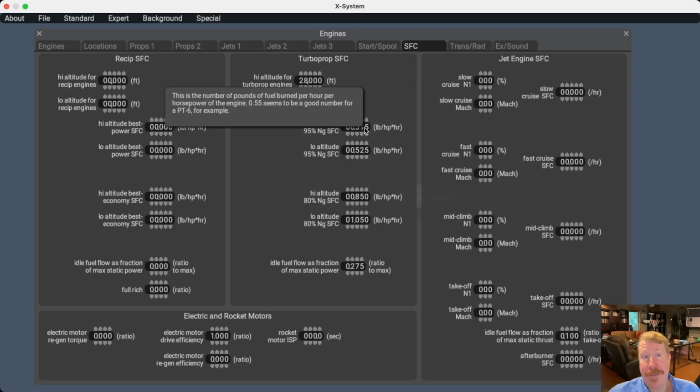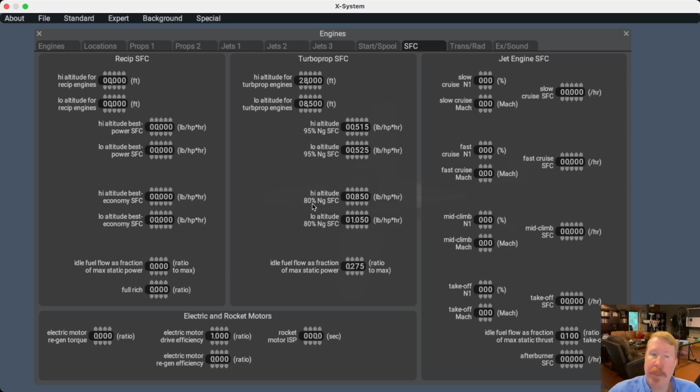It's 0.5 compared to 0.45 or so in the Cirrus. It's almost as efficient as a reciprocating engine, but only when it is spinning 100% RPM or close to it, in this case 95% RPM. As soon as that gas generator RPM slows down because you're into a low power setting, the pressures in the engine don't work right and it just turns into a piece of junk.